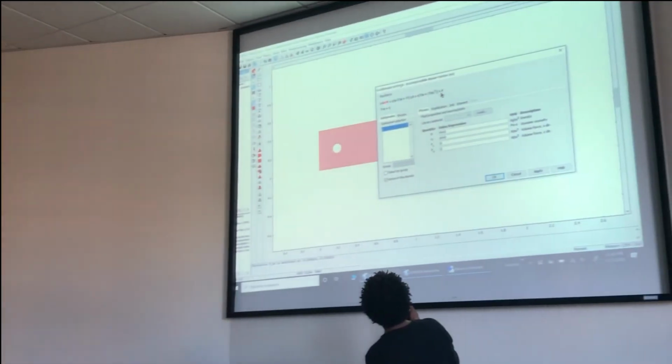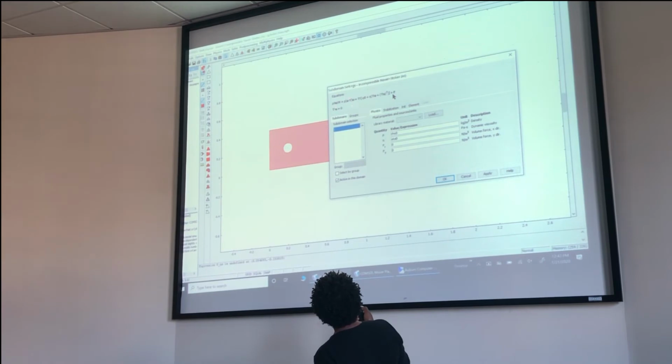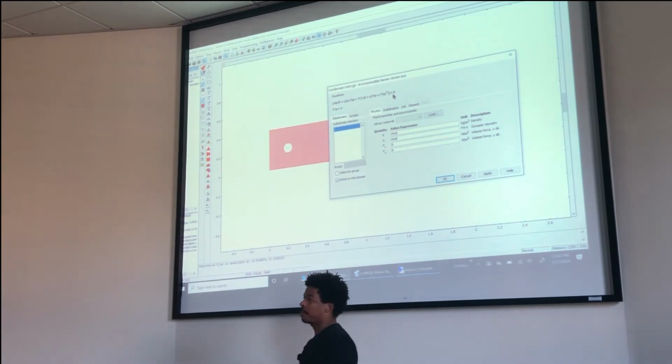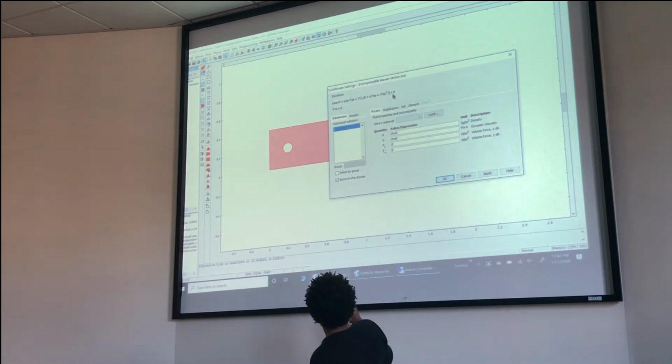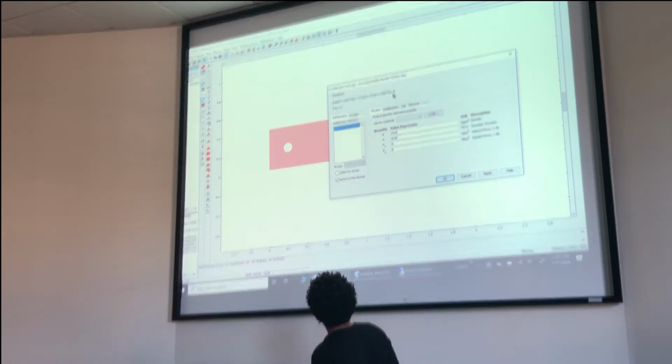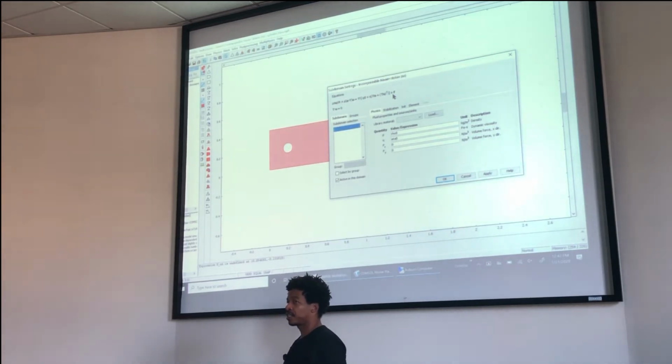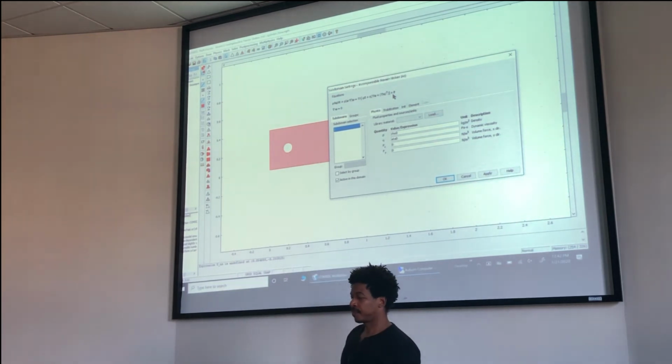Now, COMSOL is actually based upon a very long PDE that has many parameters on it, many coefficients. And what you do is you turn certain coefficients off and on to make the equation you need. So in this particular case, these are the terms that survived. So these terms right here are on. There's lots of other terms that are useful for other types of equations, but they're turned off because that wouldn't be Navier-Stokes.